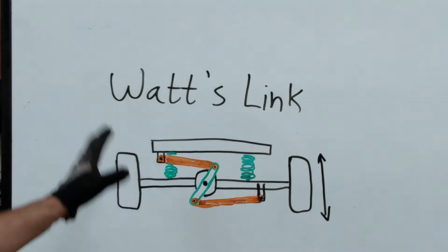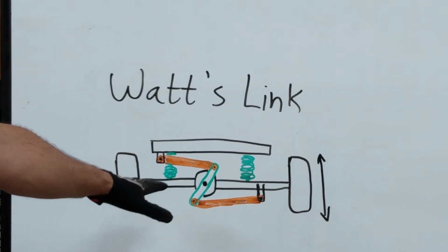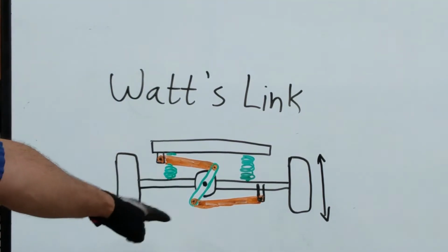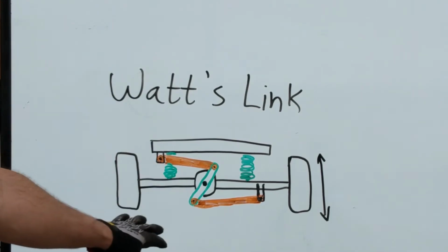This is more of a handling characteristic suspension for a high performance vehicle or for a luxury vehicle with a solid axle, as opposed to a track bar setup on an off-road situation. You get less articulation and suspension movement out of this suspension with the amount of links and the brackets and the clearances.